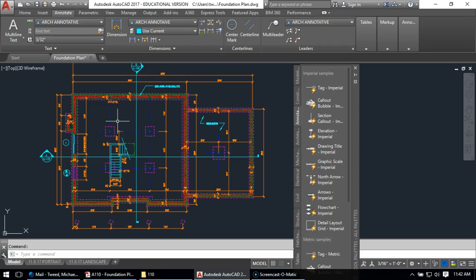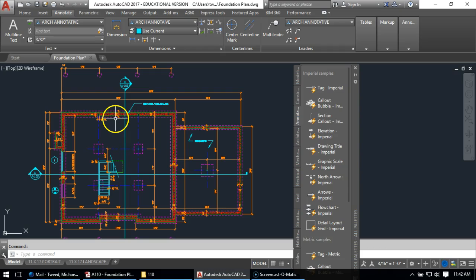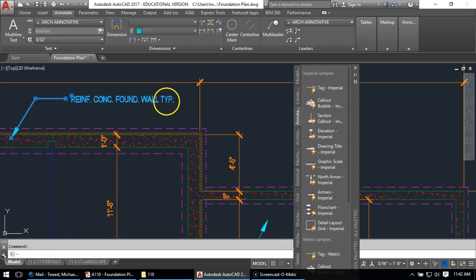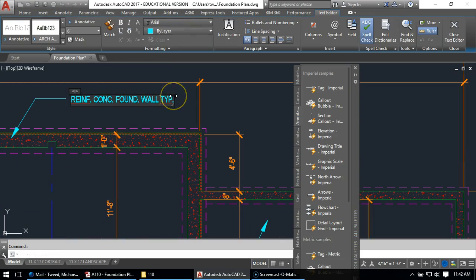There's an edge of footing, so we can skip 8 because we sort of took care of it with my alternate there. We can do 3, which is edge of footing centered beneath foundation wall. And that's, again, they use the TYP there. They're using the parentheses, so I might go and edit this to be consistent.